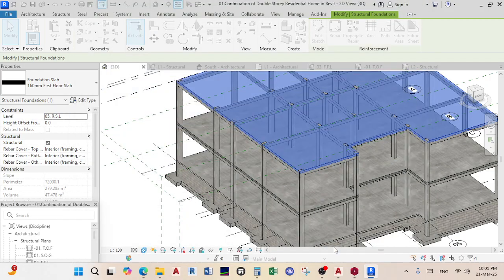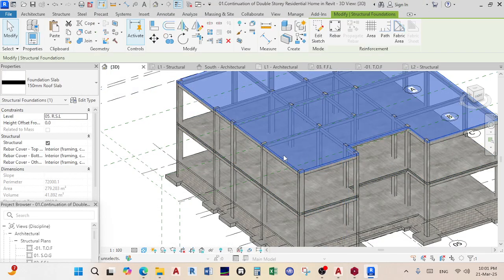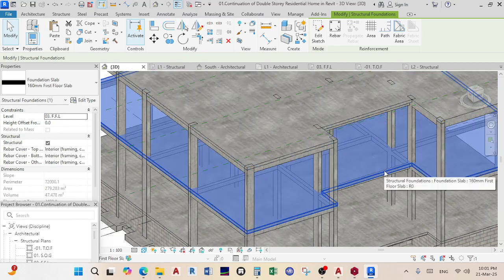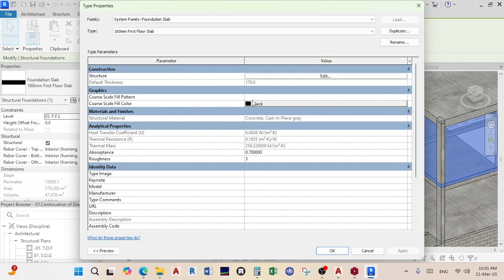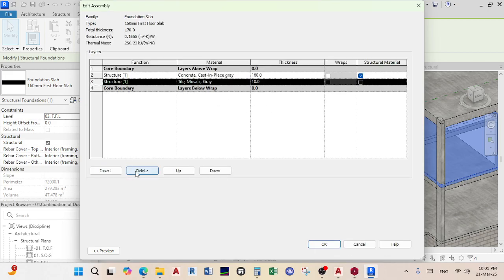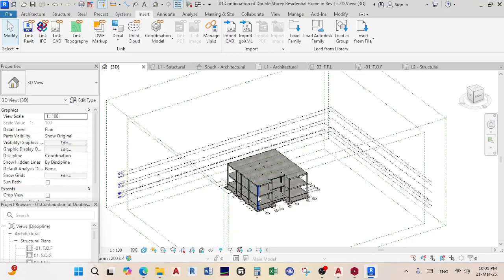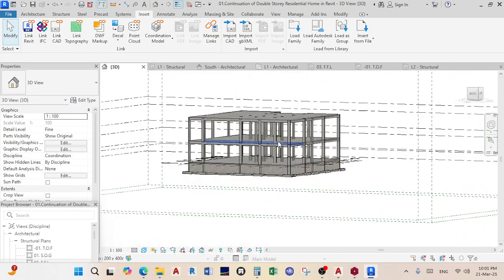I'll apply like that. So mind you, when you click it like this, make sure it says 150. Check your parameters, 150, cool. And then go to your there, make sure it says 160 or 170 in our case. In fact, let me just maintain 160. Let me delete this. Everything else will be up to. Okay. Now we are good. This is our gray structure.